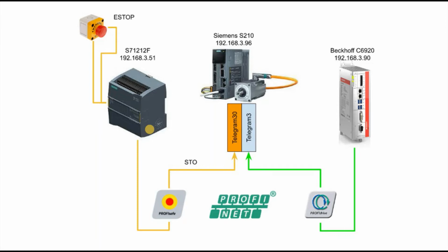So what can you do? You can just replace your PLC, for example, from a 1212 to a 1212F. But you need to consider so many things. You need to consider how many days you need to convert the program from 1212 to 1212F, add the safety program inside, debug it again, and make sure it runs properly without any problem.